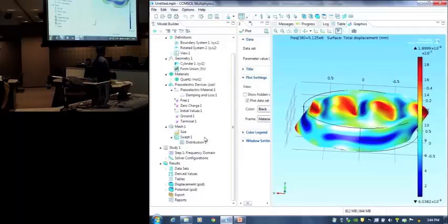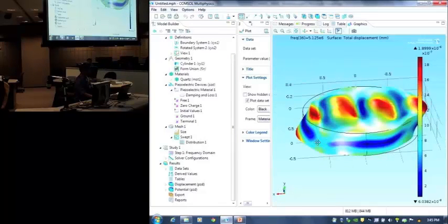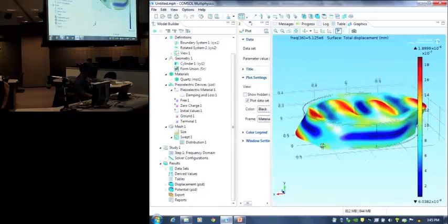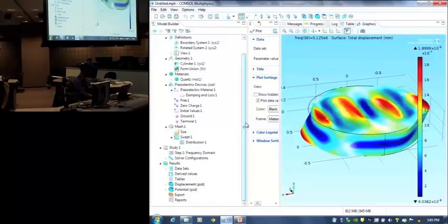But it is a good practice to use constraints in frequency domain calculations to eliminate vibration modes that you're not interested in. In this case, I already knew the frequency, so I already knew the response because I did eigenfrequency calculation earlier. So I already knew the response mechanism, so I did not think it's necessary to use any mechanical constraints.